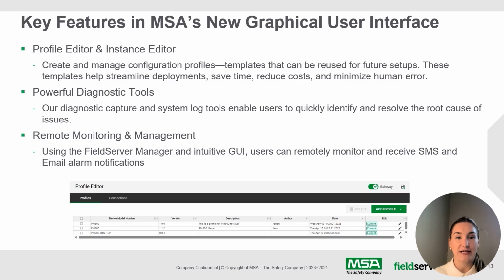Rather than configuring each gateway from scratch, you can use the profile editor to create a template that includes all the necessary points, data manipulation, and communication settings. Then, with the instance editor, you can apply the profile to each new gateway, adjusting only the unique details like IP address or device ID. That way, you can reuse the configuration, reduce manual input, and ensure consistency across all deployments. This graphical user interface also comes with powerful diagnostic tools like diagnostic captures, system logs, and health checks to help you find and fix issues early.